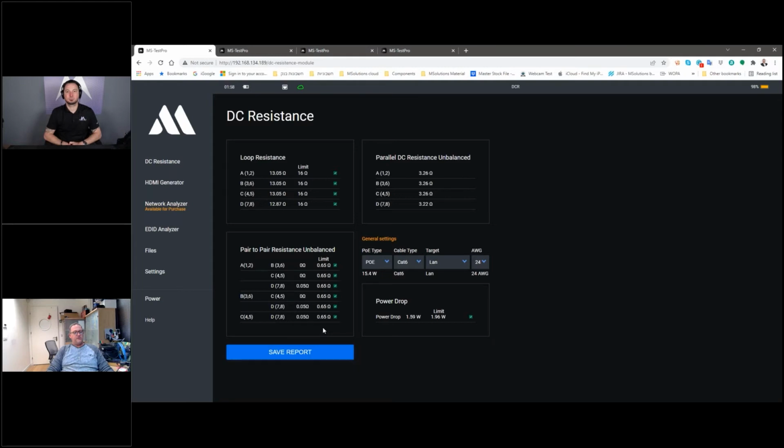If the cable is not good and we are unable to retransmit data, we're unable to receive the picture. So we get video drop or we get link disconnection, depending on the amount of error and the amount of loss on the cable itself. So what we did, after a lot of investigation of different types of cables, we came to the conclusion that most of the cables will require different limitations on how we pass them.